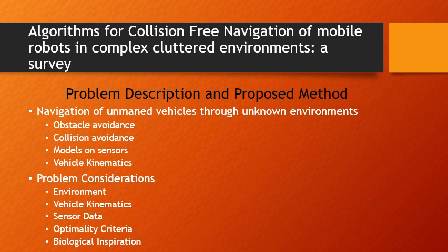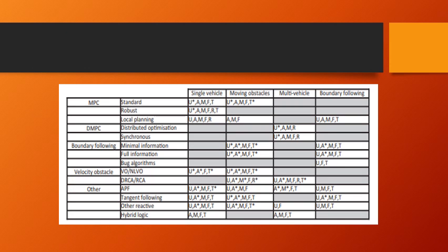In this section on sensory data, it can be defined as abstract ray-based minimum distance tangent sensors and optical force sensors. With respect to the optimality criteria, these are methods of preferentially choosing one possible trajectory over another. A combination of the following measures are commonly used. Minimum distance is used, forming two configurations without obstacles, as they have a complex effect on the optimal path present, and acceleration constraints are not present in this. Minimum wheel rotation of differential wheel robots, minimum time, minimum control effort, and optimal surveillance rate are other common methodologies under them.